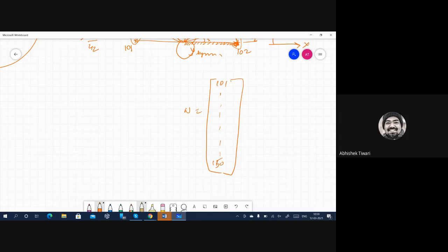So let's say take 10 data points from the initial curve in a range of 100 to 200 megapascal, because there the slope will be linear. It will be in the elastic range. So when the stress value is between 100 to 200 or 200 to 400, in that range, select some data and fit it in a linear fit, find out the slope of that. Once the slope is known, draw a parallel line at an offset of 0.002. So you know the intercept value, you know the slope value, draw a line y is equal to mx plus c and find out the intersection with the curve. And then you know what is the yield strength. You can write this code.